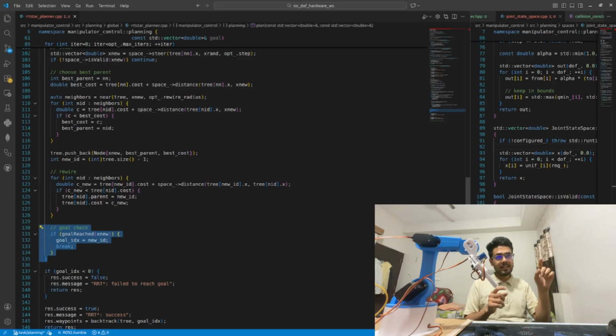Now the path is from RRT, but I should have a trajectory for it, like fitting a time curve on that path. So I will fit a curve in the trajectory space. That can be a trapezoid, or a quintic, anything you want. This is how the entire pipeline is. And then at low level there is a PID control that is controlling the motors. That is how this entire pipeline works.